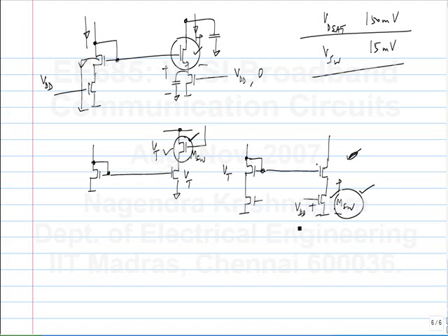But yeah, switching at the source, you can use a smaller switch than when you switch at the drain, and also the capacitance at the output of the current source is not determined by the size of the switch, it's determined mainly by the size of the current source itself. Okay. So those are the two advantages of this. But this switch will still be larger than when you switch at the gate.